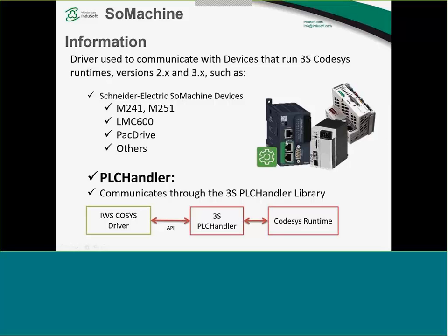On this picture here is an M251. This also works with any other device that runs Codesys. So it could be this Eaton PLC here, it could be a Wago PLC, Bosch Rexroth. So anything that runs Codesys, you can use this driver to do that. And this shows how reliable that platform is. The good thing is that the Schneider Electric SOMA family of devices runs Codesys.